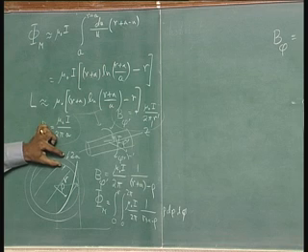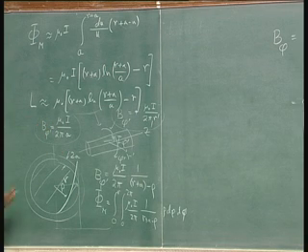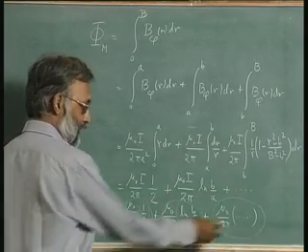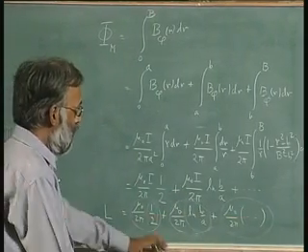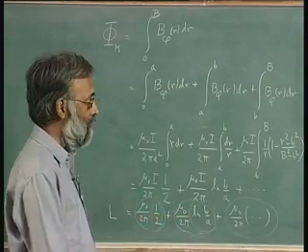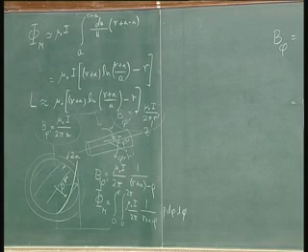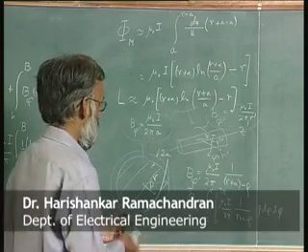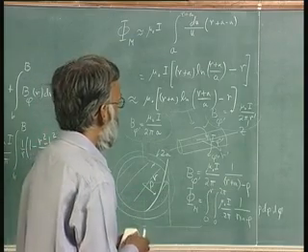I would rather have that thickness and live with the internal inductance, because the internal inductance is all said and done a rather small quantity. If you look back at this formula, this is ln b over a, whereas it is just half, and this is a smaller number than this. So, this term does dominate, but this term is present. So, in a certain sense, the issue of internal and external inductance has more to do with the gauge of the wire, and our decision of how much of the flux should be outside the wire and how much should be inside. Okay.